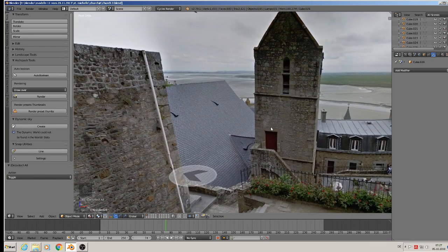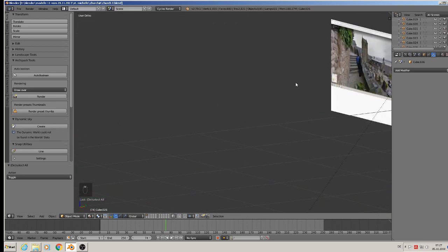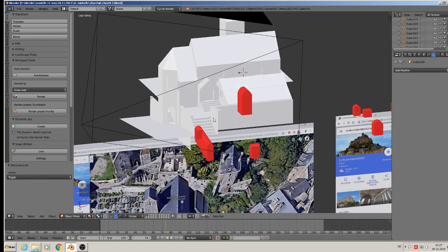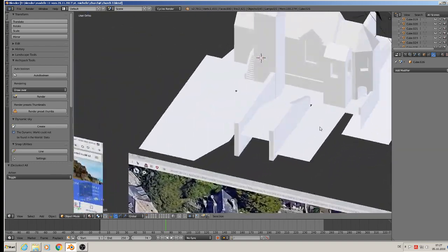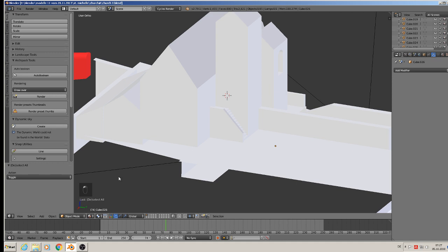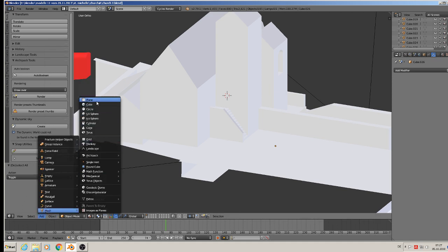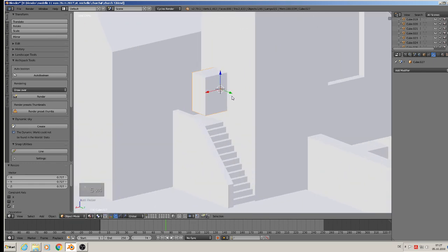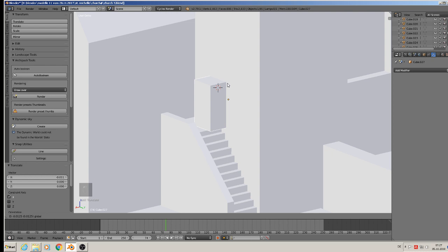So a simple hole with the roundings. Okay. And here staged. Okay, so we need a hole in there for the door. That's the first. So add mesh cube, scale down, scale Y, scale Z. That should maybe reach far enough for the door.